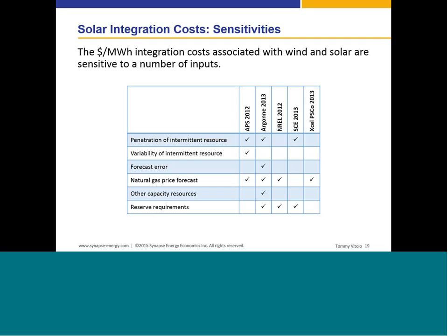At the end of the day, we see wind and solar integration costs are about $5 a megawatt hour, half a cent a kilowatt hour. And remember, these costs represent the incremental costs due to variability and uncertainty incurred while balancing the grid. The sensitivities, different physical futures matter, right? So as your generation is going to change, as your transmission is going to change, both in your system and your neighbors', those are the kinds of sensitivities that make a lot of sense to me to think about.